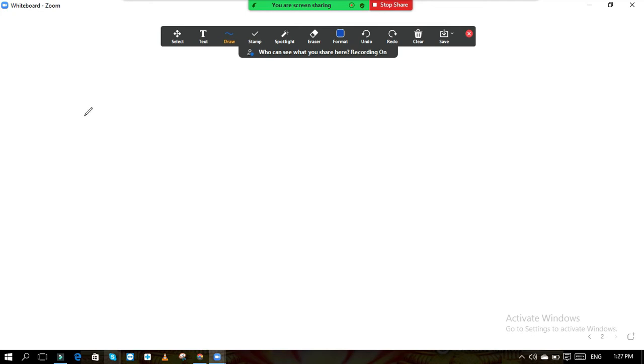Okay, and similarly, if you look at the cantilever wall, it consists of stem, base slab, toe projection, heel is also there. So there is some geometrical centroid. If you take a rectangle, where does the centroid of the rectangle lie? b/2, t/2. Okay, so loading centroid is a different concept and geometrical centroid is a different concept.